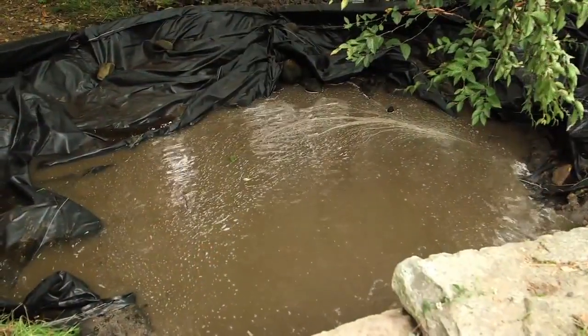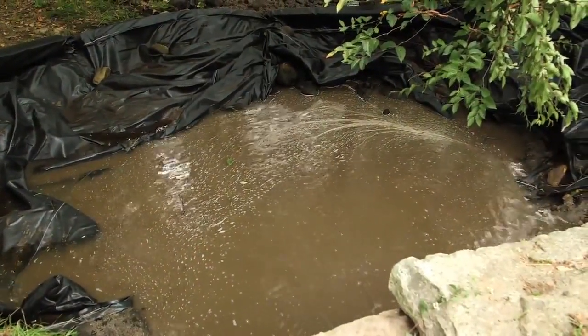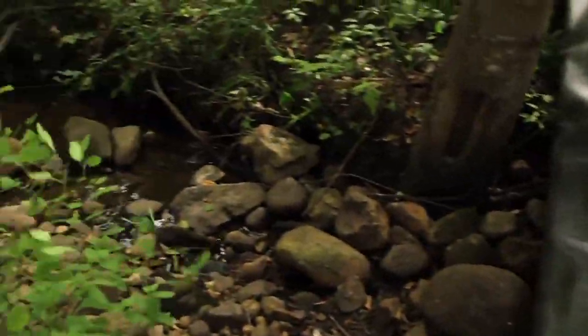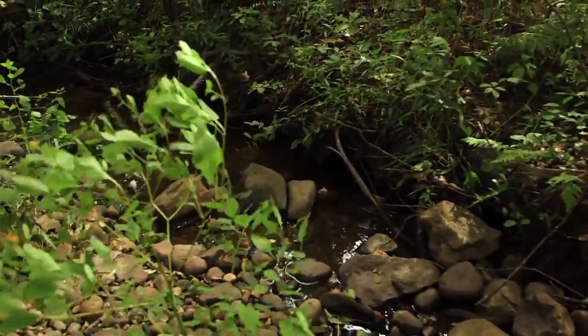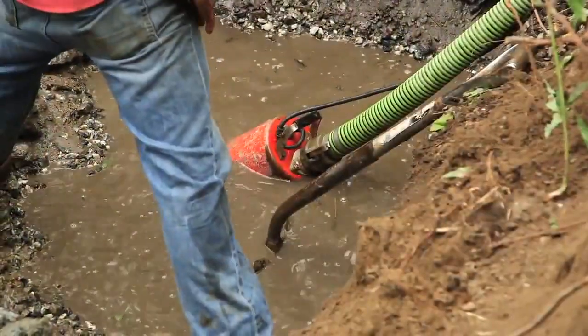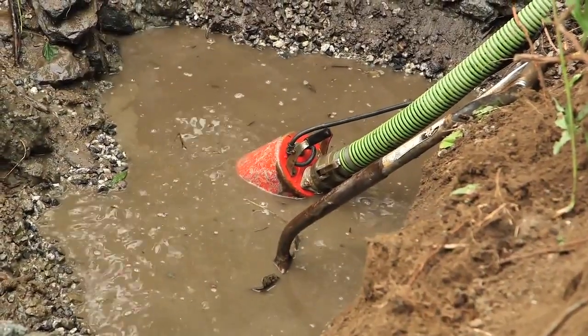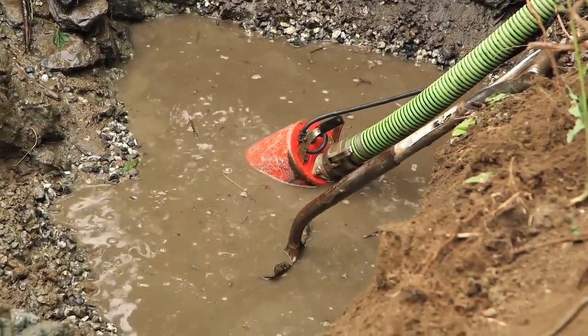As the settling basin filled, flows that trickled out over the top of the sediment basin were relatively clean when re-entering the stream. Any dirty water encountered in the disturbed work area was pumped into the woods a far enough distance from the stream so sediments were removed prior to water re-entering the stream.